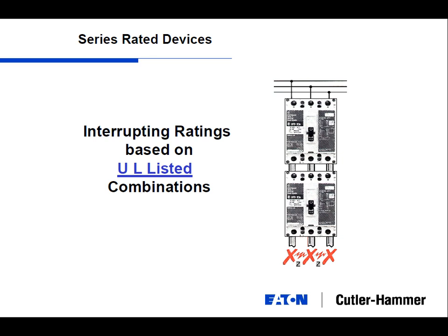It's like really big equipment in the motor lab. I'm not sure how much that particular one is. If you have a lot of motors off that panel, but remember these are lab motors and not loaded. One of them draws 90 amps still unloaded, inrush. Yes, inrush. But these are small motors that we use in the lab. They're not loaded. They're not running an air handling unit or a pump.